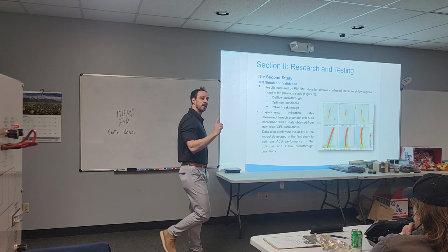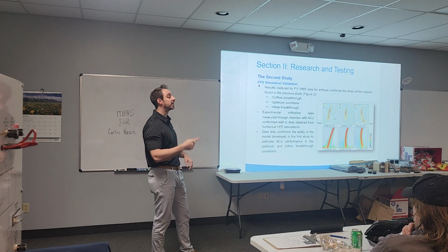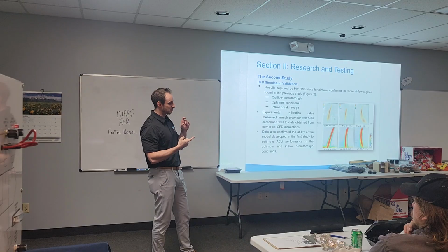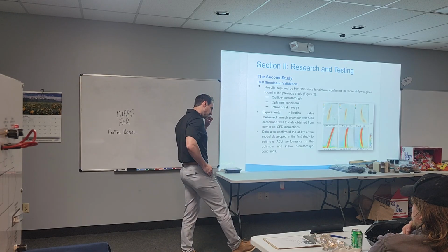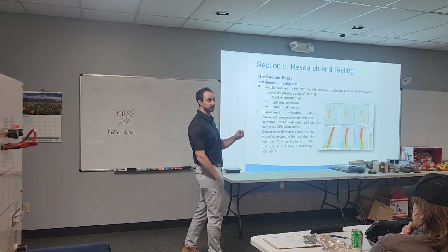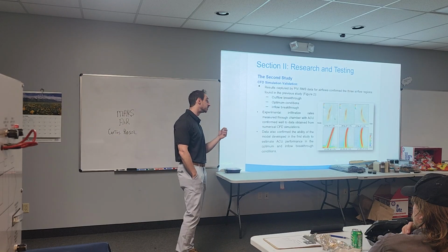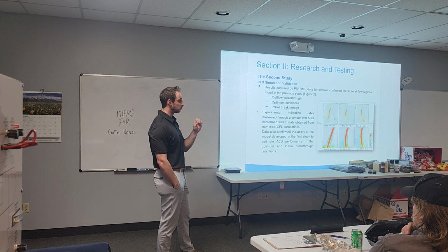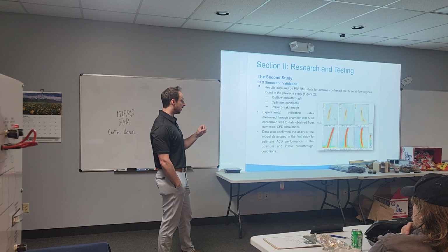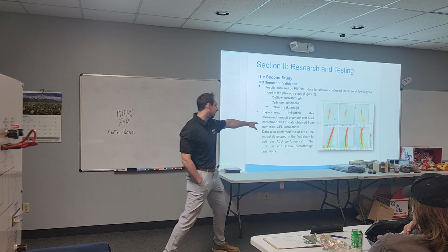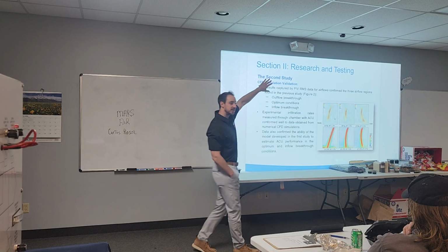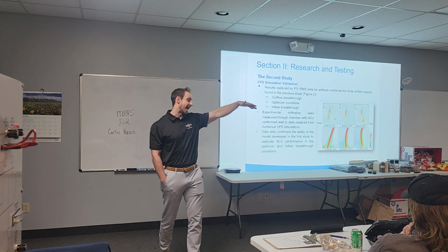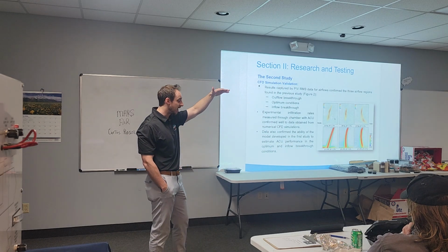The biggest thing with air curtains, and the biggest problem, is that if you get a complaint that an air curtain is not working, the majority of the time the building's not balanced, and specifically it's the negative pressure. That's really the hardest thing. If there's negative building pressure, then you're not going to get this profile. You're going to get that far right one, but depending on how much negative pressure, maybe halfway down the door, maybe a quarter way down the door.